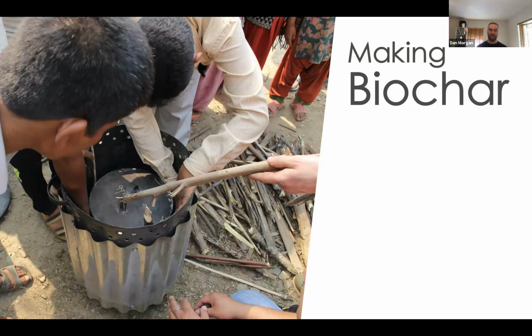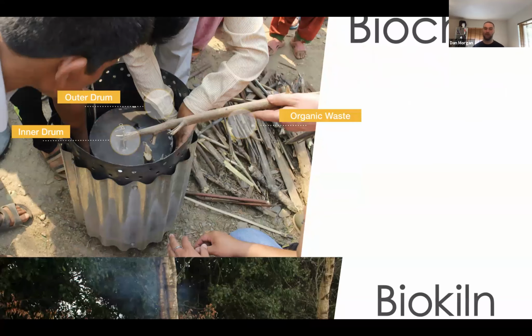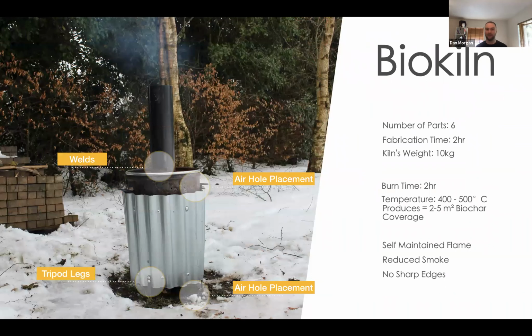in an oxygen limited environment in this internal chamber, which through a scientific reaction called pyrolysis takes out all the moisture and just leaves carbon ready to be turned into biochar. So as this goes through here, we take general organic waste that you can find, and we've tested everything from rice husks to banana peels, tangerine peels, but also offcuts of wood, leaves, sticks, and really the rule of thumb is you're looking for a moisture content of under 22%, which generally you can feel by touch.